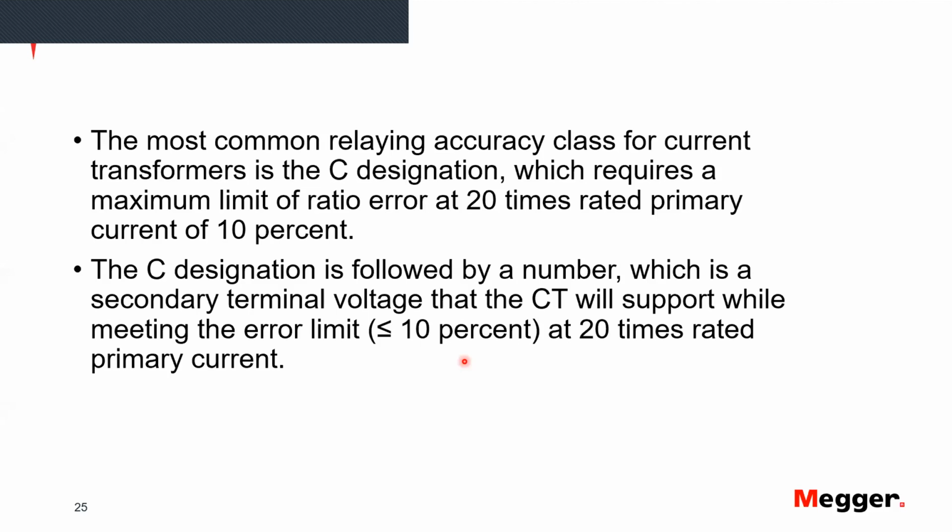maybe a 3% accuracy at rated current. If it is a very good CT, it can give you maybe 1.5% if it's classified as both metering and protection. But when it really matters, which is when I'm having the fault, the CT will typically, and I think that's something that Sughosh showed in his presentation, saturate, and you get errors.